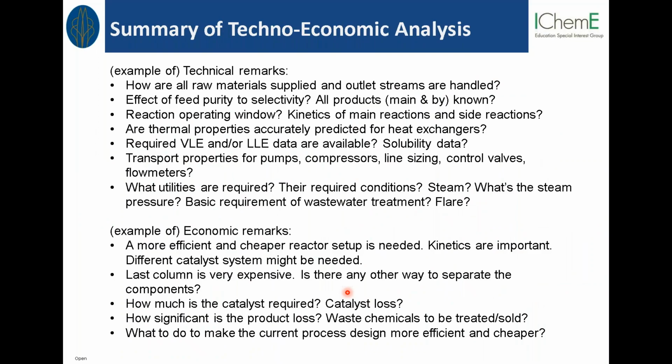So if I put them all in summary, this is just an example of some general remarks, so technical remarks. How are all raw materials supplied and outlet streams handled? And then what is the effect of purity on selectivities? Do we know all the products, main products and byproducts? Operating windows, properties, what kind of utilities? All of these are required, like a list of questions that we need to have before we can say, yes, we are going to select this process over the other, or this is going to be one of the selected views to be evaluated further. And also the economic remarks, as we discussed before.